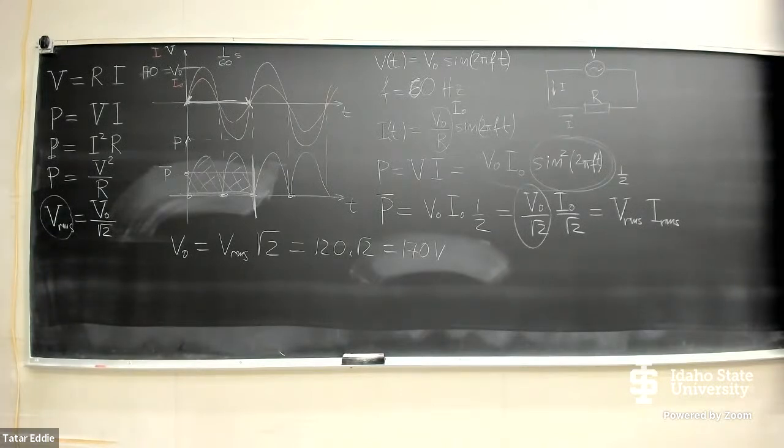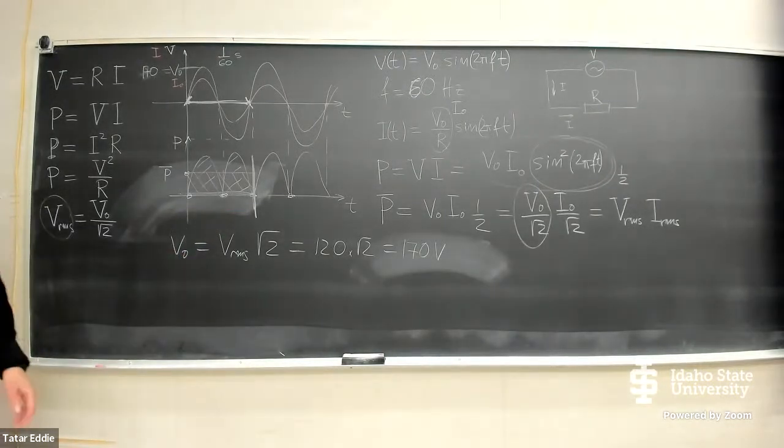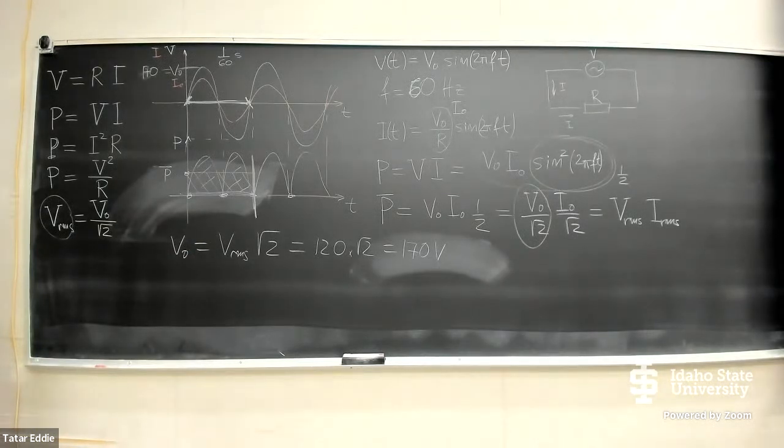Thank you. So the amplitude is 170 volts. Well, it changes by a few volts during the day, as when you have more consumption, usually the voltage drops, but the amplitude is around 170 and the RMS value is about 120. This is for the United States.